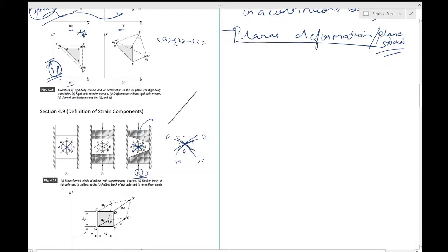I have already explained to you how this curve can be replaced by a tangent, so nothing new over here. And the deformation of the small area is then similar to that of this. So now there are straight lines everywhere, and that's how you can approximate non-uniform strain as a uniform strain if you focus on a very small area around your point of interest. That's the important part.